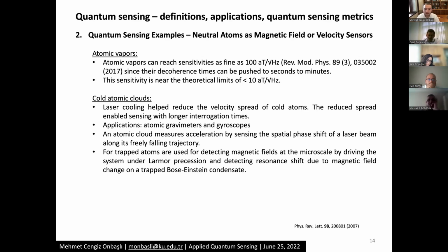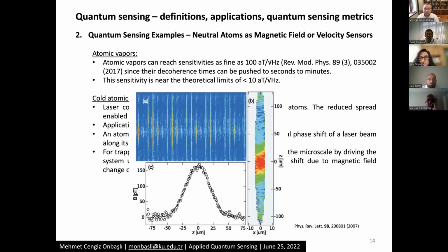As a result, we end up with an optical pump or optical probe readout difference. So the spectrum of readout is going to change because of the magnetic field difference. And as a result, we detect the magnetic field intensity or its frequency. But of course, there are many nuances in these measurement steps, and that's what we are going to study in the next few slides.